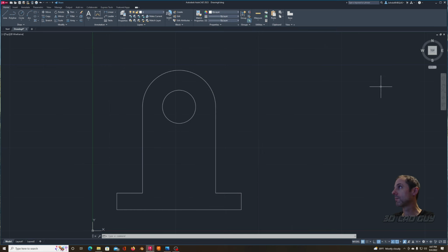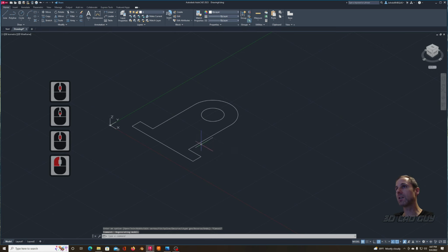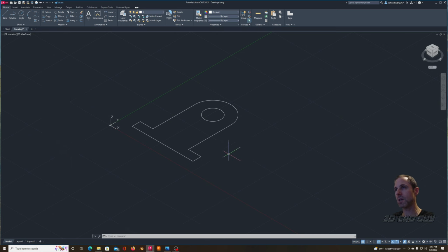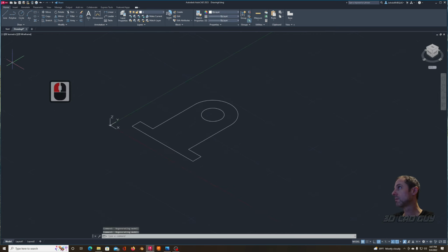At this point, we will rotate the UCS, which I can go up here and do like this. The last few versions of AutoCAD do this in a similar fashion. Looks exactly the same. So from here, I like to look at this perspective so that I can see the actual shape and everything. Some of you may not like that. You may want to give it a different angle. You can control it, whatever your preference.